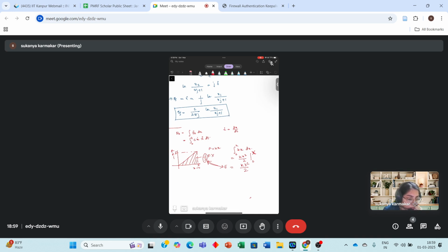And the remaining amplitude in that case will be 200 minus 177.1 mm, which is 22.9 mm. And we have been taught that for starting a cycle, the amplitude should be more than f by k. It is true. So after 7 cycles, it will take one more cycle or it will stop.